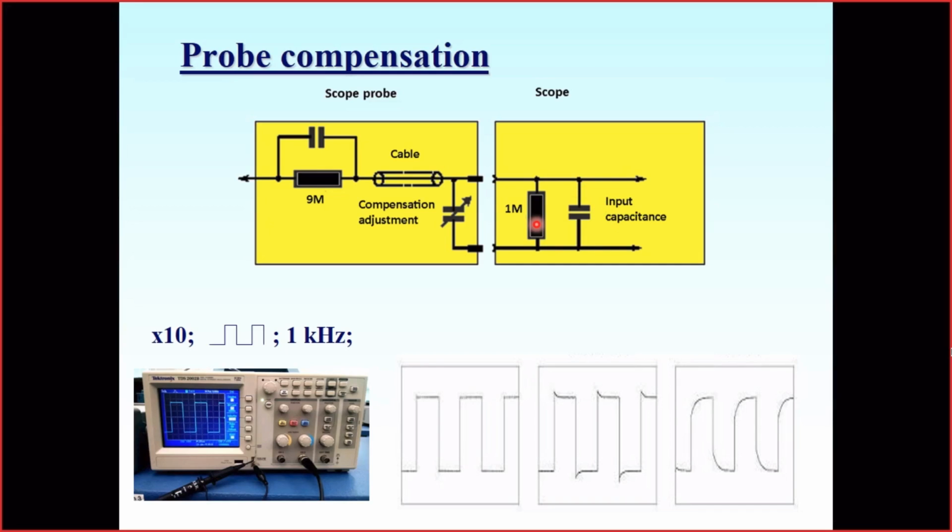When we design our measurement circuit and want to be sure that we measure a real value, not a shifted or incorrect value, we have to take into account the actual electrical parameters of our meter. When we know the input resistance is 1 megaohm and the input capacitance is known, we may make a correction and know the accurate measured voltage.